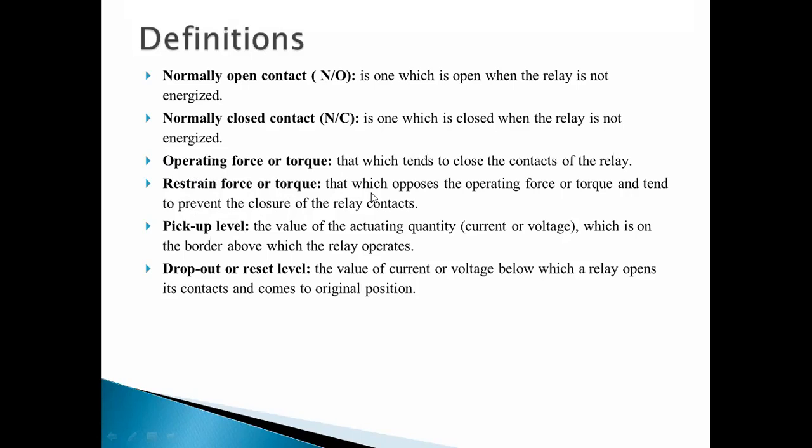which is helping you to operate or do some work, right? So there is one operating coil and another one is the restraining coil. Operating coil is what actually it is doing: it is attracting that arm so that the relay contacts will get closed, okay, to operate the circuit breaker. But this restraining coil is forcing that arm to open the contacts, means there is one spring, okay, opposing that operating force or torque.